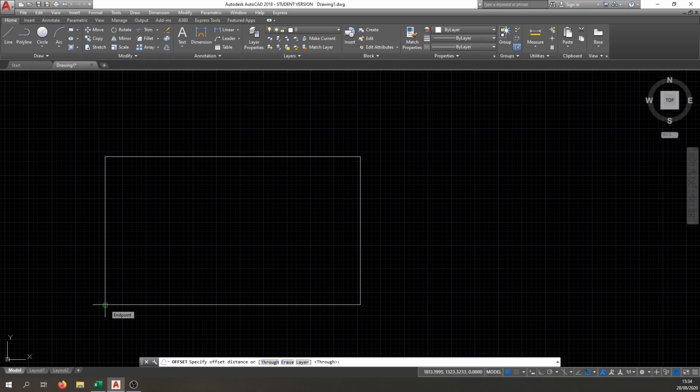So you can actually have a look. If you hover over the endpoint, don't click anything just yet, hover your mouse over the endpoint and bring it in a little bit, and if you look down here at the coordinates, you can roughly see what size your line is. So you can see my extension there, saying an extension by 50 units. So say I want to offset that in maybe 10 units. So press 10.